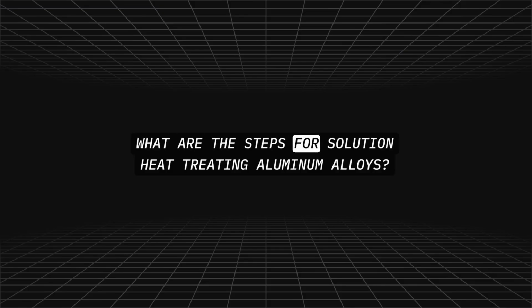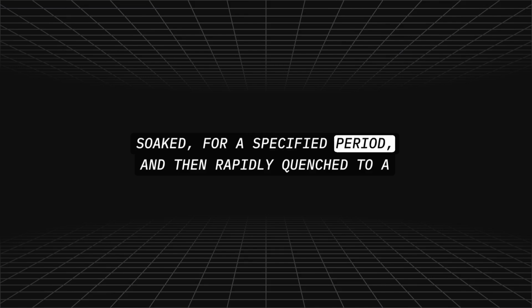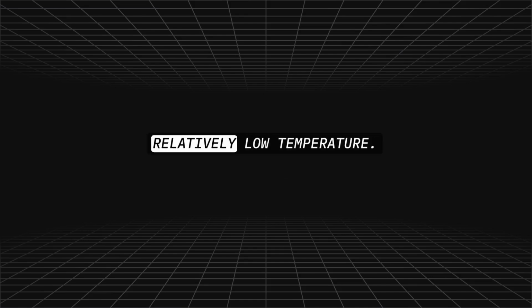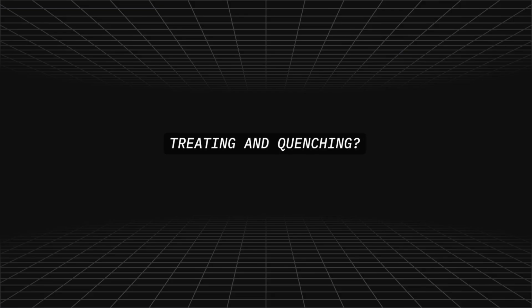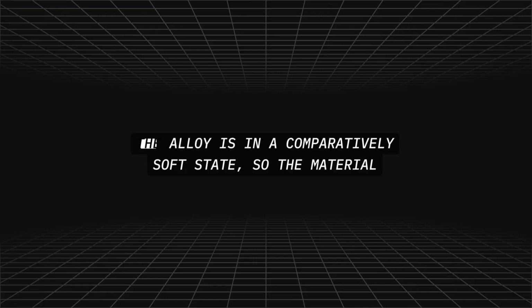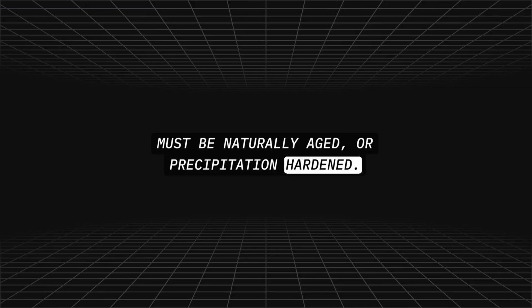What are the steps for solution heat treating aluminum alloys? The alloy must be heated to a predetermined temperature, heat-soaked for a specified period, and then rapidly quenched to a relatively low temperature. In what state is aluminum alloy immediately after solution heat treating and quenching? The alloy is in a comparatively soft state, so the material must be naturally aged or precipitation hardened.